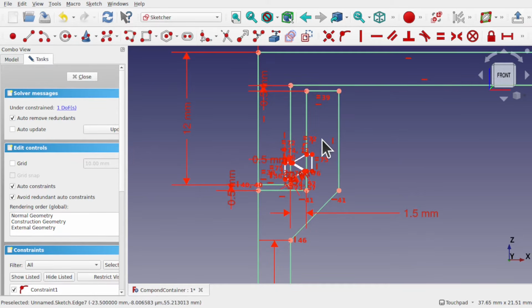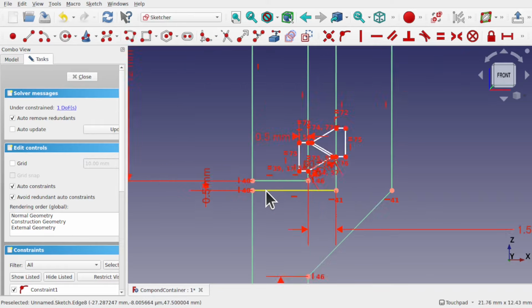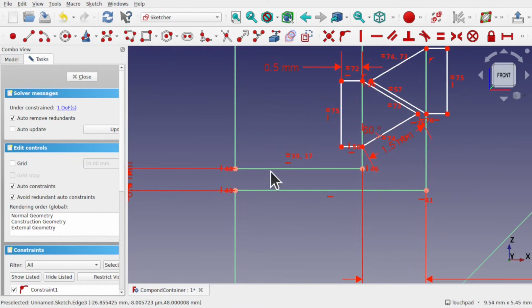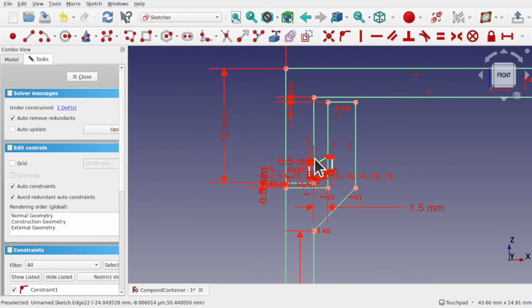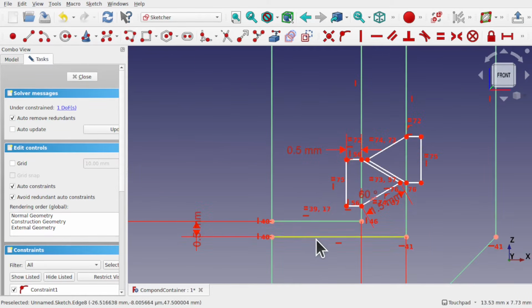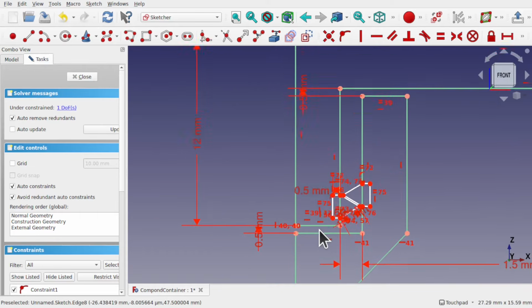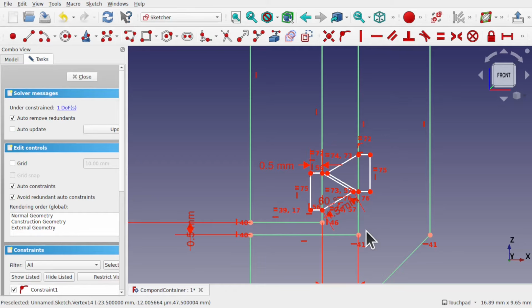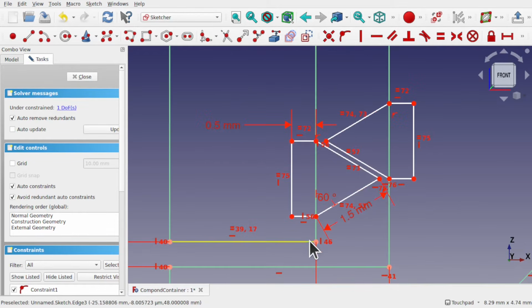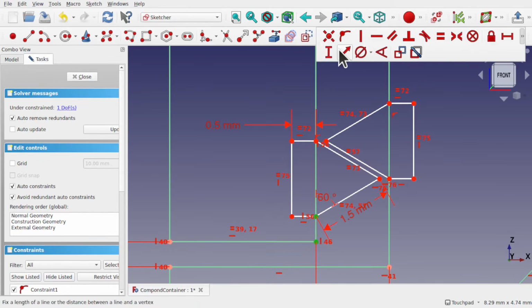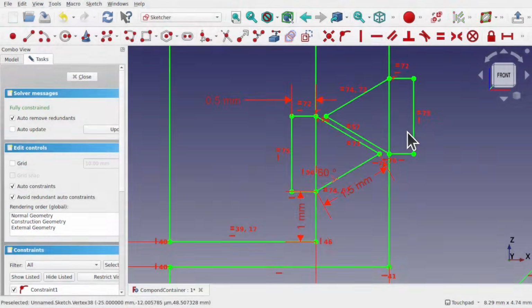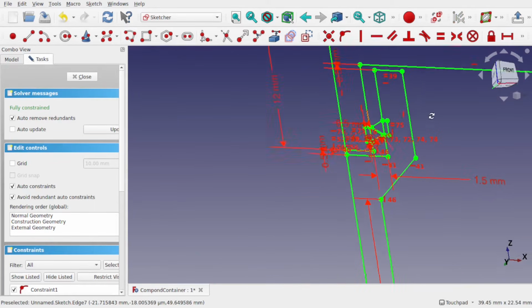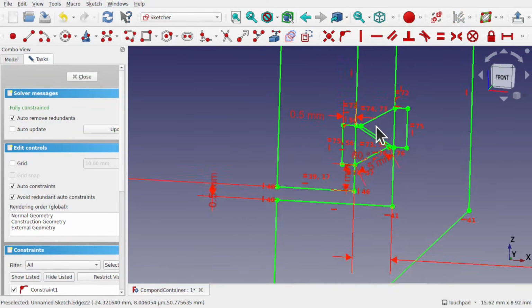So the top here. We want to have the lid move freely over this thread and make a seal at this point here. So this will seal down. So we can keep on screwing this up and tightening it and having these pressed together to make a nice seal. So we mustn't stop the thread at the top or the bottom. Also, we just need a couple of turns in there. So if I wanted to, I can come in and set some height between these two, of about 1 millimeter. And we have our thread profile in there ready to go.